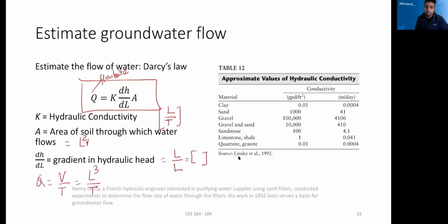So one thing to note here is that when you have a site for remediation or assessment, you have to think of what kind of materials they are made of, because that determines their hydraulic conductivity. For instance, if you know it is a sandy soil, you know sandy soil is highly porous, things move much faster, or it doesn't stick to the water that much. So you see the hydraulic conductivity of sand is much higher.